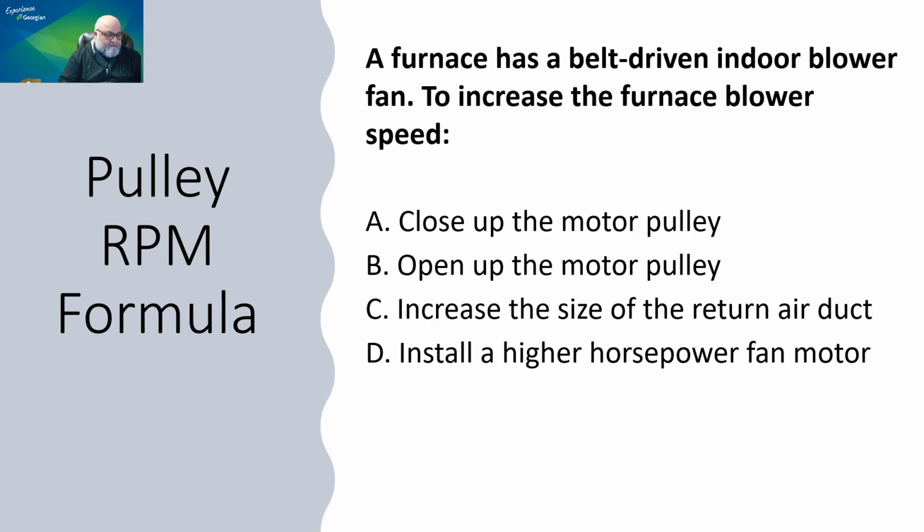One last question here. A furnace has a belt-driven indoor blower fan. To increase the furnace blower speed, what do you do? A, B, C, or D? And the correct answer would be, okay, let's have a look here. So we know that to increase the blower speed, we need to increase the diameter of the motor pulley. That's also one of the three rules. To increase the diameter of the motor pulley, you have to close up the motor pulley.